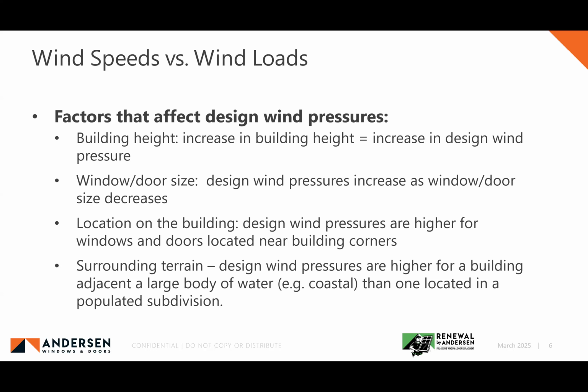The window or door size. And this seems counterintuitive to most people, but as the window size decreases, design wind pressures increase. Like I said, that seems counterintuitive. Most people tend to think, well, if I had a bigger window, it seems like it would be a higher design pressure.